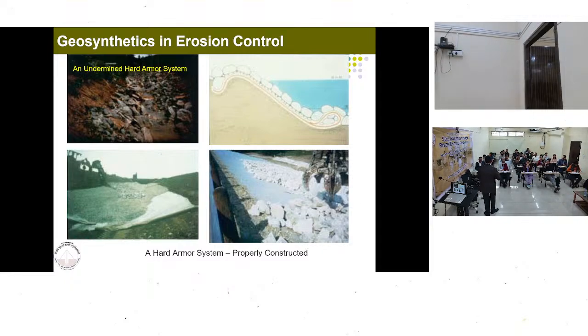At the Farakka barrage, a lot of silt load is being settled. The Farakka canal has relatively much cleaner water. So it is being apprehended that because of that much cleaner water, this canal, in order to maintain its regime, is picking up sediment from the river and the canal, which has led to the degradation of the canal by more than 4 meters.